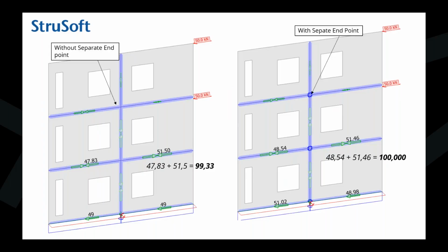So there's always a contradiction about which wall should have the corner point forces. In FEM-Design, you don't have that problem. And if you use separate endpoints, you are in perfect balance of external loads. So the story shear forces match the shear of the wall connections. So your model will be perfect if you do it like this.